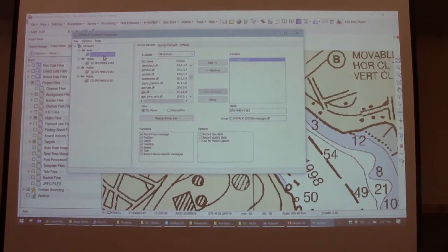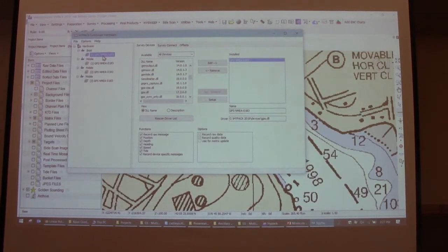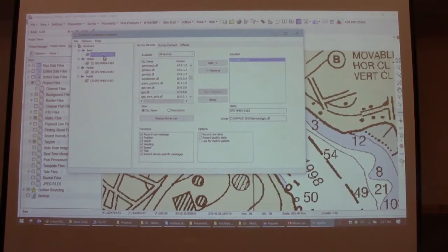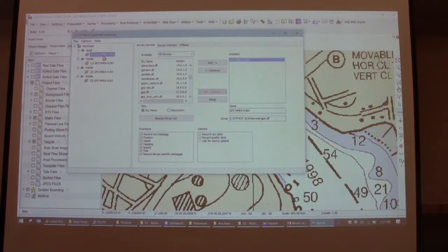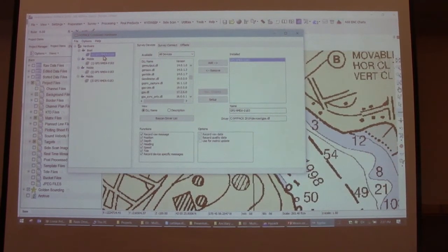But they were able to separate the 4 separate boats and then have all 4 of the crosshairs showing up. So for example, if you had a 40-foot wide boat, you had them set up one crosser was 10 foot. In an ideal world, the display would show you 4 transducers collecting data going across and you're covering a 40-foot swath. It only ever shows just the one transducer.